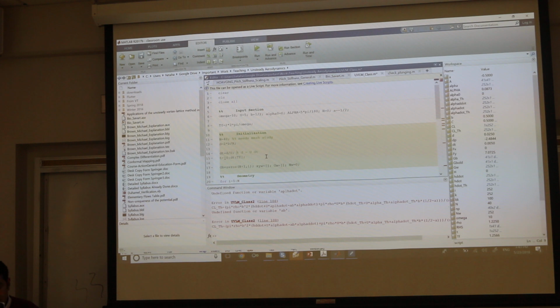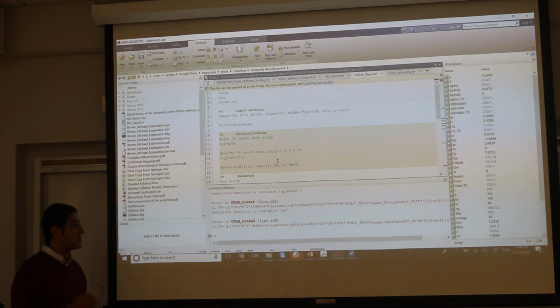The same for delta t. So delta t, I told you that this is like a rule of thumb. Once you determined your panel width, it's just divided by u infinity, but again, maybe for different applications it would be different. So here you need again the same thing. You need mesh study. So this is a spatial mesh, and here is your temporal mesh, right? We're doing discretization in space and time.